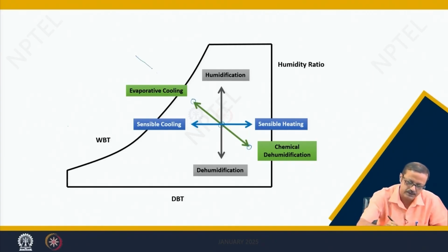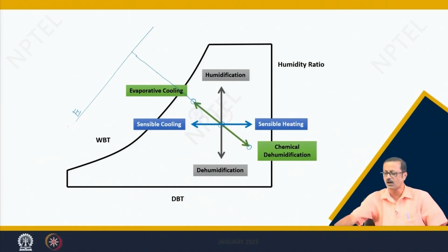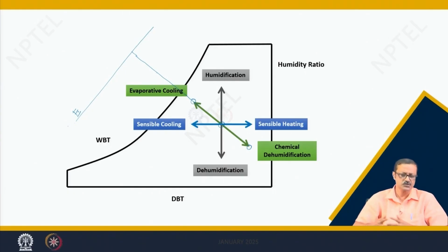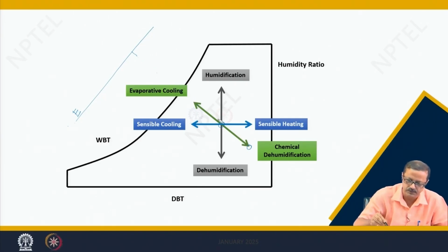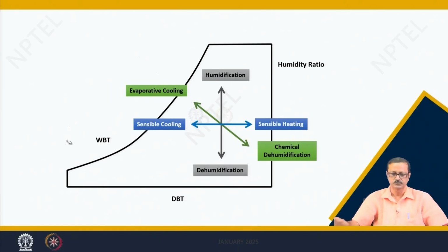So, in here, as it is parallel, perpendicular to the energy axis or the enthalpy axis, there will be almost no change or negligible change of the energy. So, that is one of the psychrometric advantages we can take, and we can manipulate that, and we can think of something like passive cooling systems or maybe low energy cooling systems.